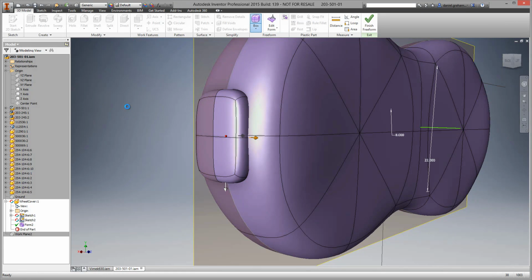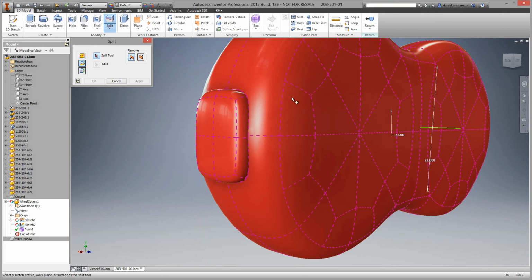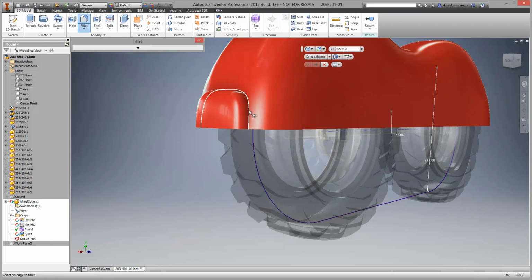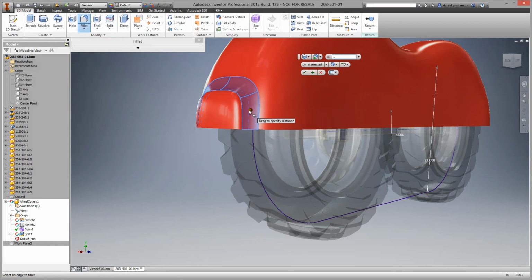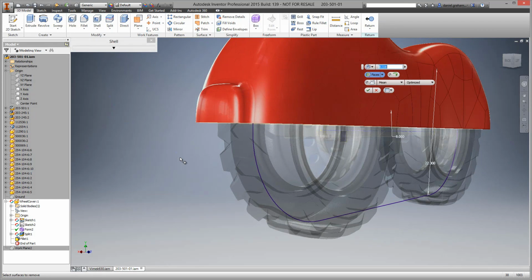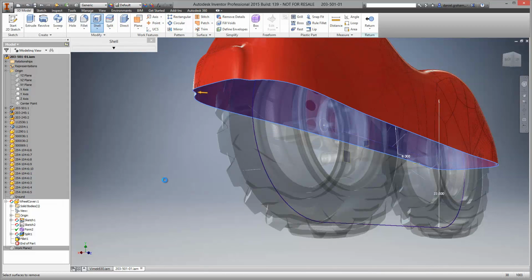That's one of the advantages of using this technique, this modeling area in the software, is that you are always ensured of curvature continuity in your model. Now, with previous tools that users had available to them, this sort of control was not easy to accomplish, and as you can see, it's pretty much automatic here in Inventor 2015. So we have the box shape. We just blended it into the rest of the overall fender.